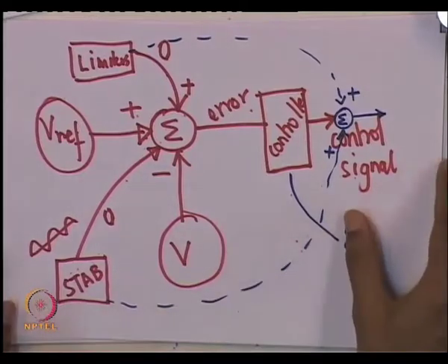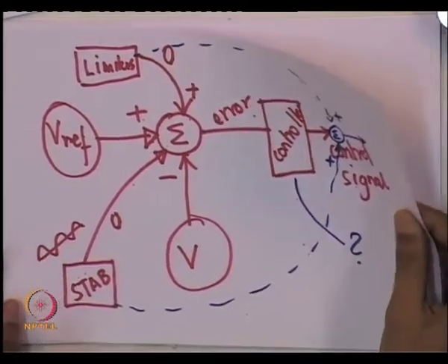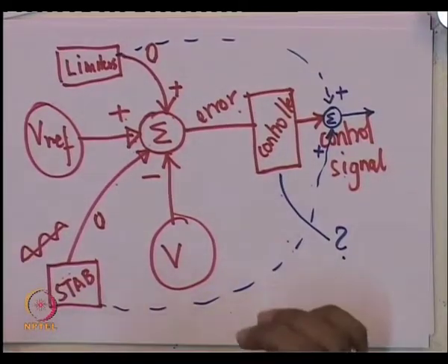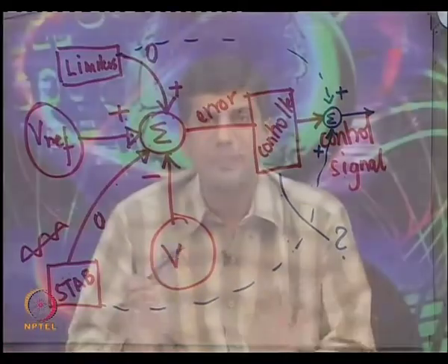Most of the excitation system control system representations which are available in the literature come in the form of block diagrams. So, you should be able to write down the dynamical equations or the differential equations or the mathematical functions which really correspond to these block diagrams.